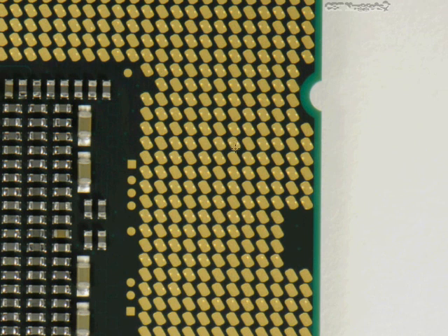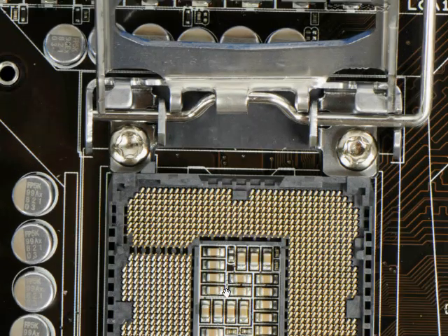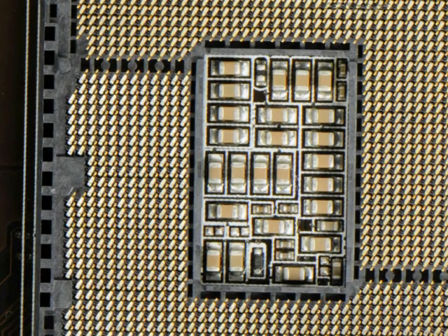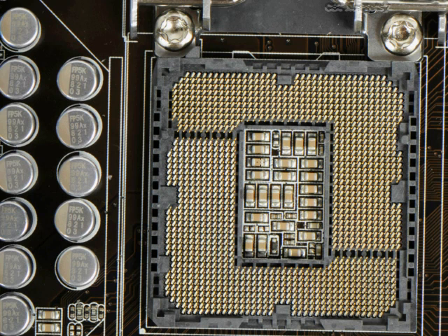These are ball grid, land grid arrays. These are actually little balls that have very little dimension to them at all, but they go into this kind of a socket, and we don't use pins anymore. You see, those pins a lot of times are very fragile, easily bent back, and so forth. Well, these are just lands, L-A-N-D-S, where the bottom of that processor just rests on top of these, and it makes it much easier to install. It's still keyed. If you look at the corners, you can see some differences in all the keys there, so you don't install it sideways or something like that.